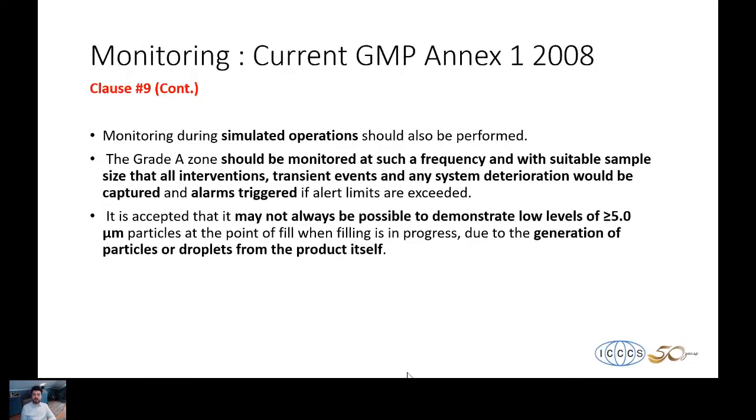And also, this doesn't mean a 7/24 up and running particle monitoring system. When we say online, most of the people think that you have to monitor 7 days, 24 hours. That's not true. Before your production, you should take at least half an hour of preparation time, and during the entire production, and right after production until the cleaning cycle, you have to monitor it.